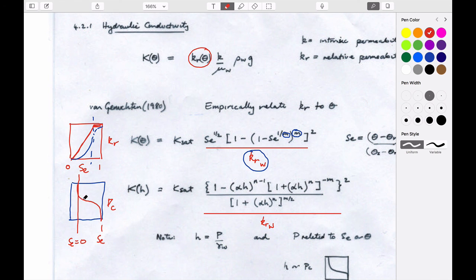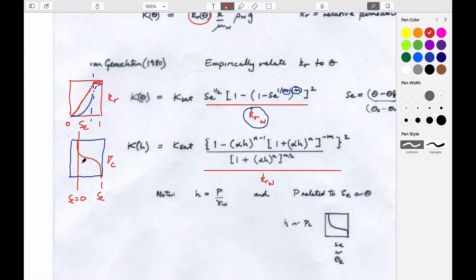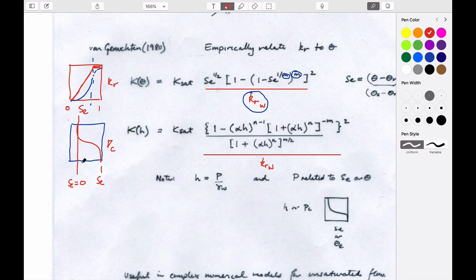The drying curve on the previous discussion we had, and now the relative permeability term, which we can also now define. And so we don't have to guess them and don't have to substitute these simple x curves that we've used in the past, but we can actually construct them should we want to. The reality is that in numerical models, we'd like to use these kinds of very accurate curves there. But for many intents and purposes, for the things that we'll do in this class, these kind of back-of-the-envelope calculations, we can probably get away with somewhat slightly simpler relationships.